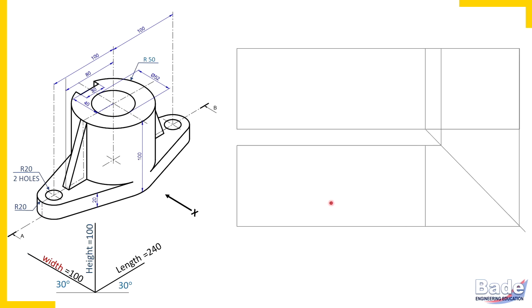Now let's proceed for parts. Let's focus on the base plate first. So when you want to construct the plate, its largest surface that you should draw first. Largest surface of the plate reveals its shape. Now shape of this plate appears in the top view. So naturally in remaining 2 views, this plate appears like a strip of thickness 20 millimeters. Let's focus on the top view. So curved edges first, then principal edges, and then non-principal edges. Do you remember the procedure I've given you?